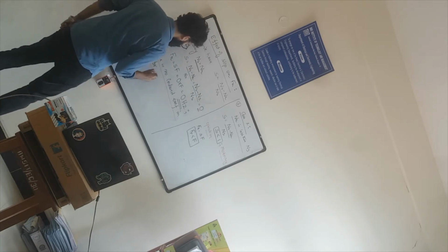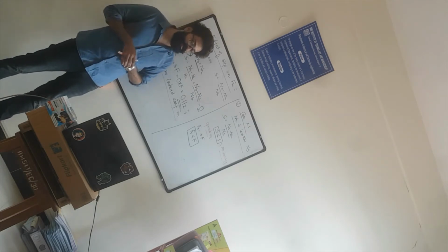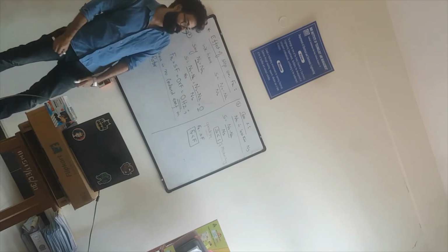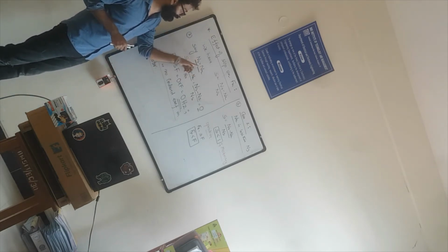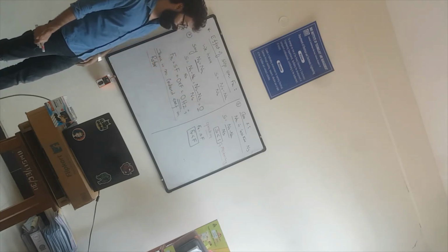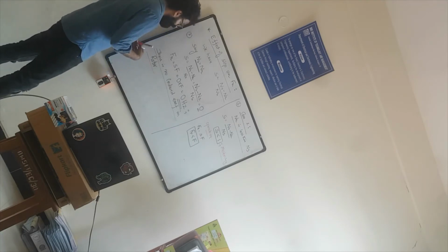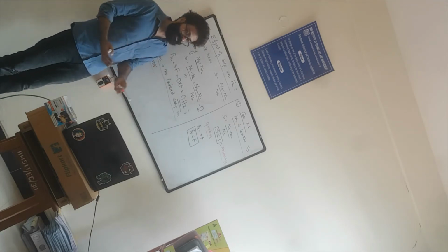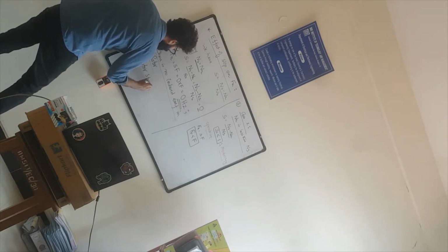Okay. So that is the reason I was telling in the beginning that if you have to have any rotation, you have to have some relative speed. So if you force the rotor to rotate at synchronous speed such that Ns is equal to Nr, the slip becomes 0, due to which the frequency becomes 0. Okay. Now, when the frequency becomes 0, what happens? The rotor stops, right? Because there is no frequency, no EMF, no torque. When torque becomes 0, the motor stops. Or you can say the rotor stops.